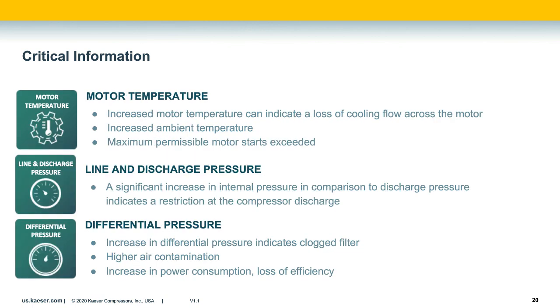Other critical information is motor temperature. Similar to oil temperature, it's a good indication of loss of cooling flow, but in particular across the motor. Overloading the motor will increase the motor temperature.